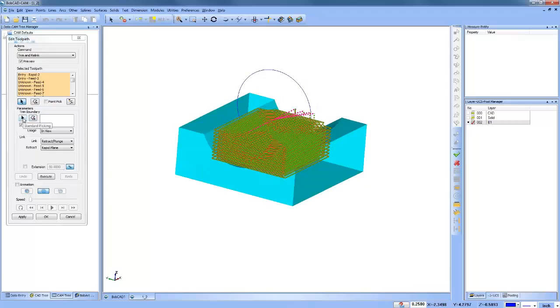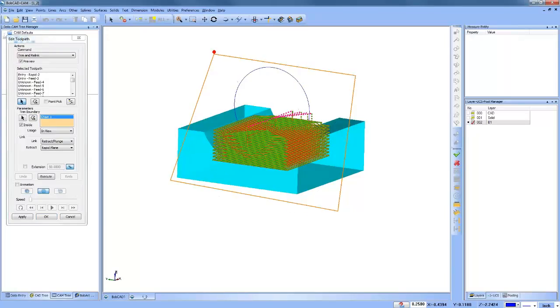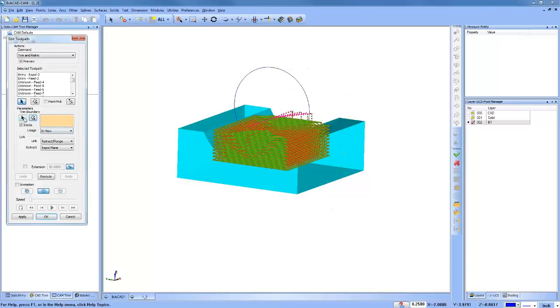So instead of the standard pick, I can do the Polygon pick. And basically, it just draws a polygon out and then would give you a boundary. So it picks up this boundary here versus the standard picking. Like the standard picking, I can select my chain or my arc that I've drawn, okay, where the Polygon pick is based off of the point locations that I pick for a boundary, okay? So hopefully that makes sense. Let me delete all this. Standard picking, I'm going to pick the chain up that I have here.